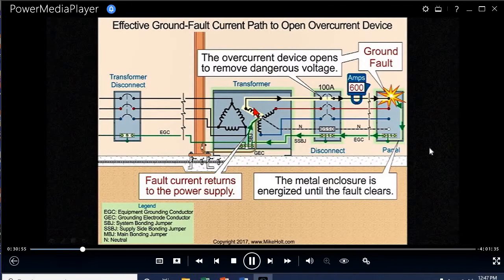I'm assuming that if we had enough fault on, let's say, phase A, it's not going to be evenly distributed over to the primary side. Eric, you're the engineer here. If I put a 600 amp fault on phase A, can you calculate how many amps are traveling to the primary? Because it's not going to be an even ratio, because we're only taking up one winding. It isn't like it's 2-wire in and 2-wire out. Yeah, sure, you can do that.